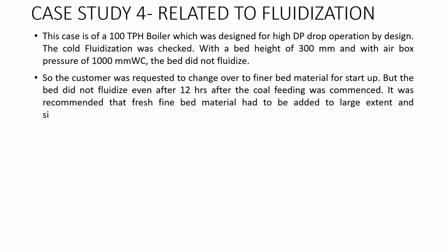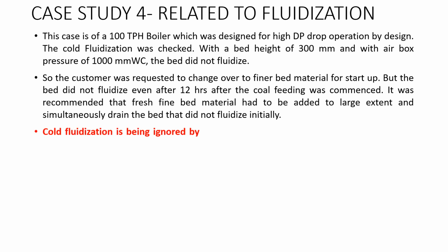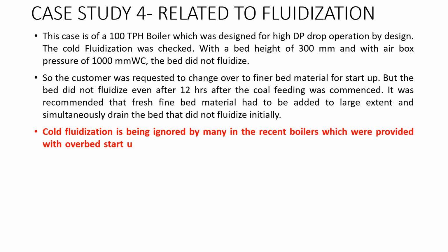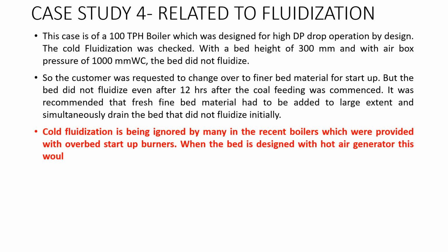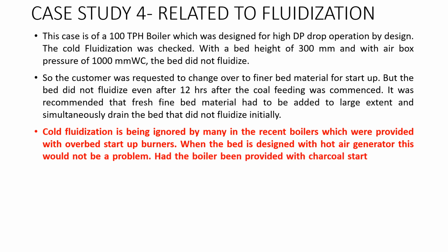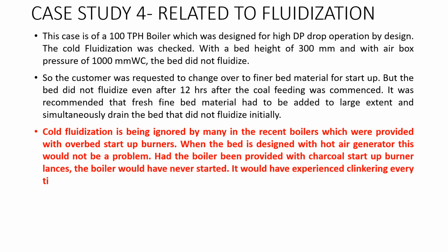even after 12 hours after the cold feeding was commenced. It was recommended that the fresh fine bed material has to be added to a large extent and simultaneously drain the bed that did not fluidize initially. In this case, the cold fluidization was ignored, as it is ignored in many of the recent boilers which were provided with overbed startup burners. When the bed is designed with a hot air generator, this would not have been a problem. Had the boiler been provided with charcoal startup burner lances, the boiler would have never started. It would have experienced clinkering every time.